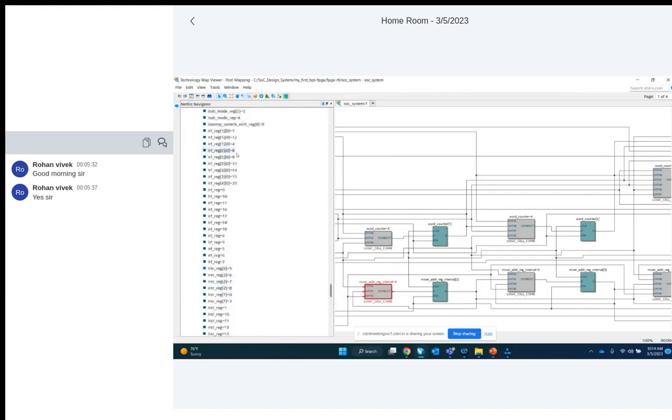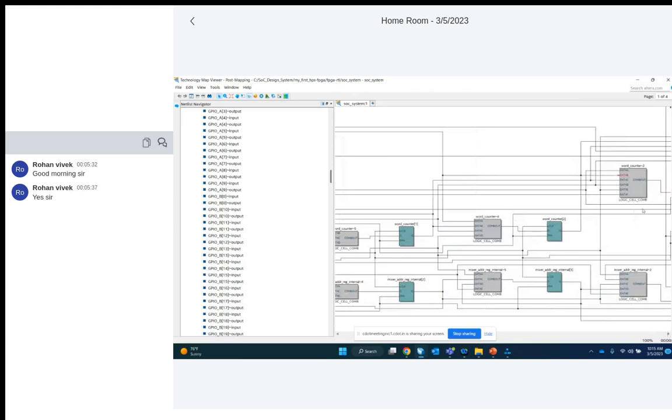Okay, this is the place where they are available. You can see that. What are the outputs? If you select this, it is a 5 input, so this is only 3 input. You select 1, 2, 3, 4, 5, 6, right? You can select the 6 input lookup table. So we can scroll this here and select this entire lookup table.